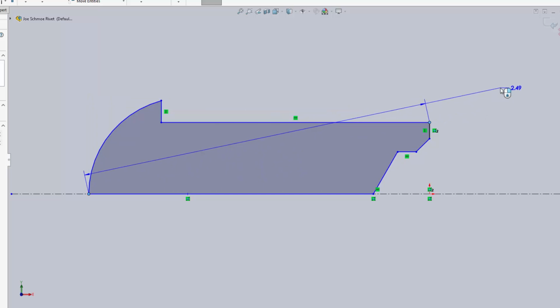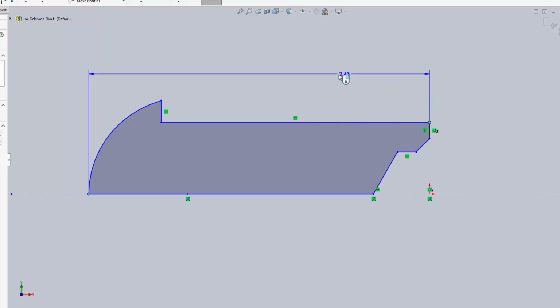In fact, if it's not this obvious, you might just say, okay, I'm going to take that, and it might be wrong. How do we avoid getting these decisions? Well, don't use points if you can avoid it. So we're going to go from, instead, point to the line. I'll show you one more time. I'm going to go from the very top. Can't avoid using a point there, but we can use this line. If we use this line, we know that it is going to be with respect to this line, which is going up and down, which means it has to go left and right. There's no other way that this dimension can work. So if at all possible, go from line to something, and maybe even line to line.